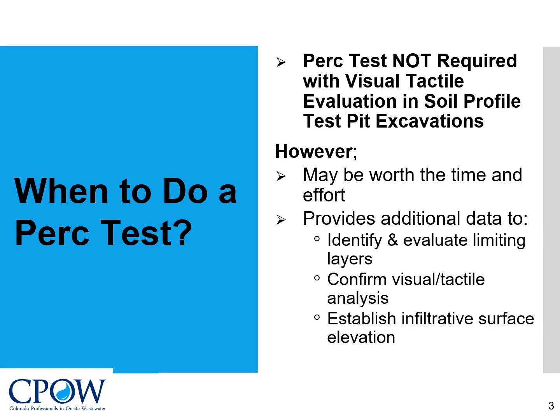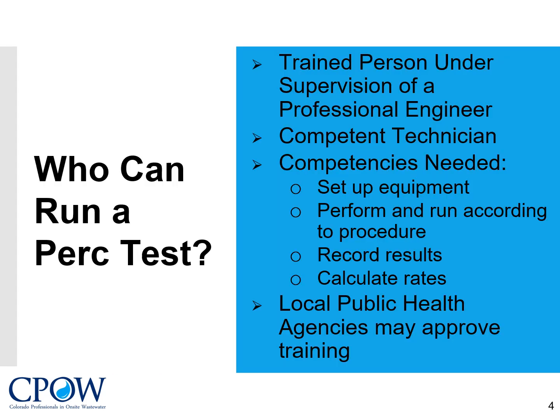We've seen situations where there has been construction traffic over the area that was set out to be the soil treatment area. Also, where you see fill soil, you may want to conduct percolation tests. This provides additional data to identify and evaluate limiting layers, confirm visual tactile analysis, and establish infiltrative surface elevations.